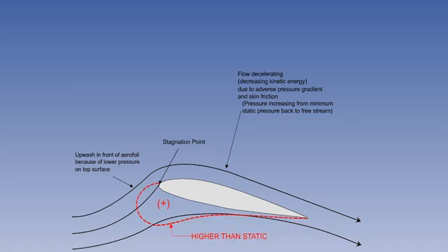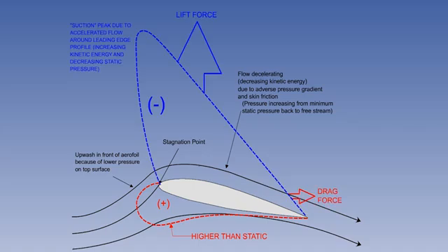The pressure distribution is shown here, with the highest pressure concentrated around the stagnation point and the low pressure extending up and forward to a peak above the aerofoil, with the pressure differential creating the lift force indicated. Also shown is the force, drag, which acts against the forward movement of a wing and is caused partly by the lift itself. Lift and drag are fully covered in subsequent lessons in the syllabus.